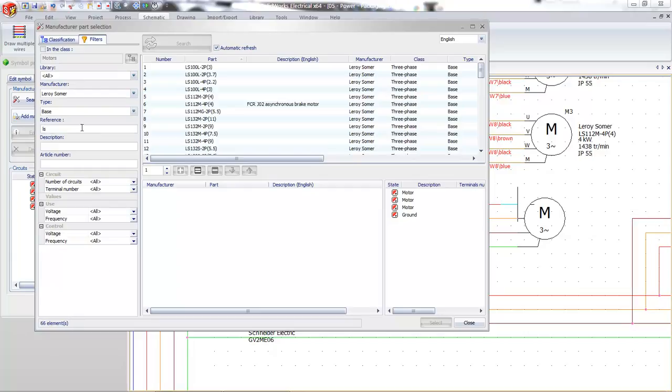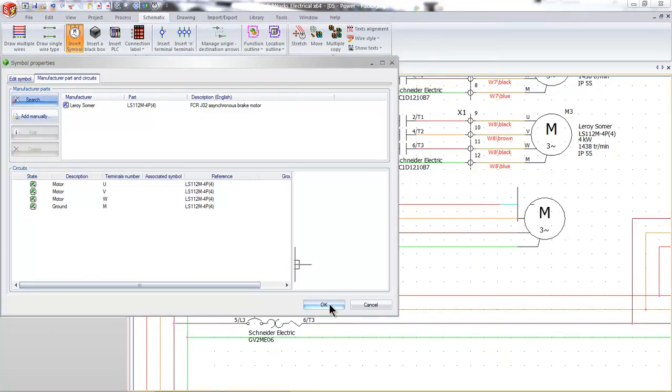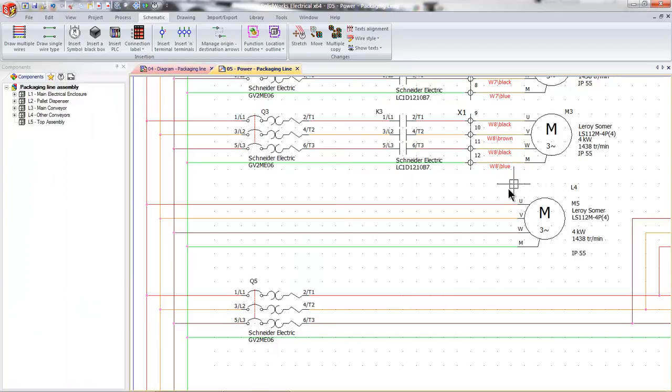So we can focus on the proper component very quickly by typing a substring of the component that we're looking for. So now we're down to 66, and that's the one I want to use. By selecting a component, it's showing us that the circuits will be satisfied. The symbol turned green, so that's good. And now we have the metadata information associated to the manufactured part.